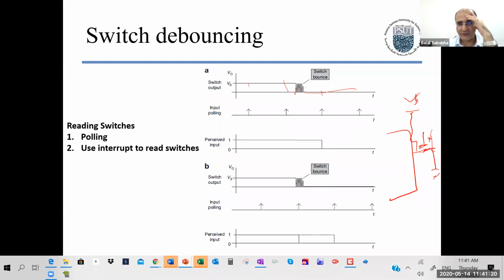So this is a disadvantage of polling, and we did examples right before when we were learning interrupts. I push the button, nothing happens until after some delay, because until we get to execute this instruction that reads. So see, the actual button push happened at this point, while you were able to notice it at this point, because the time between the readings was high.